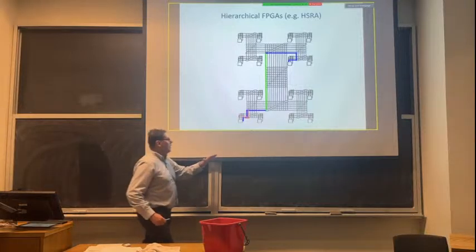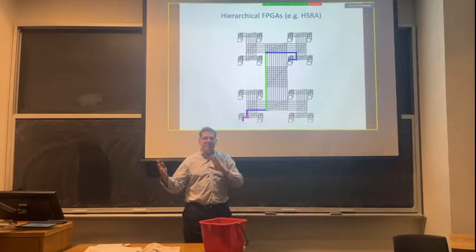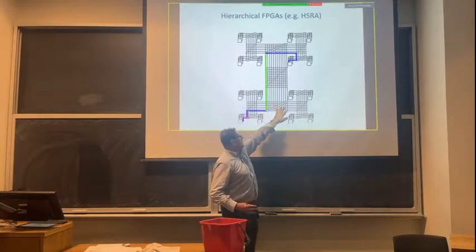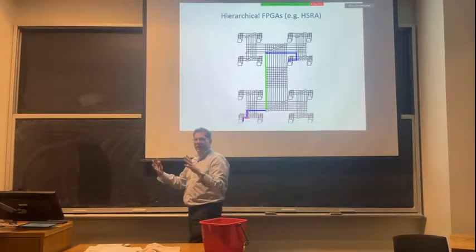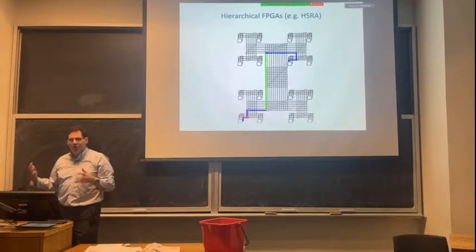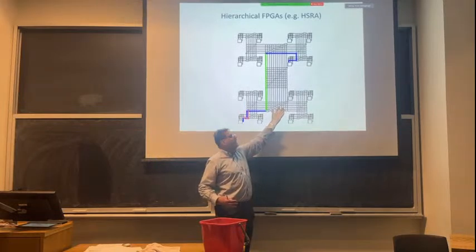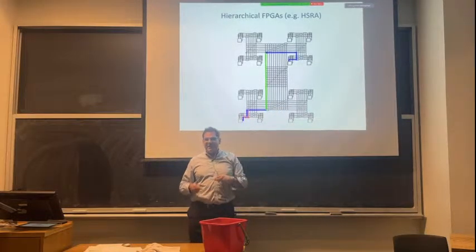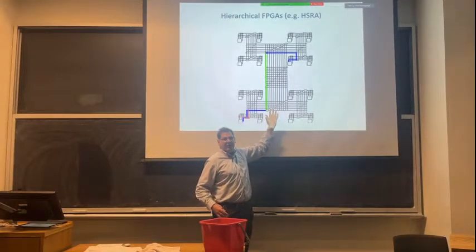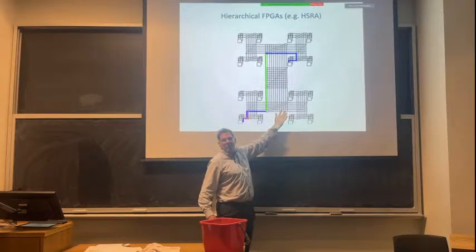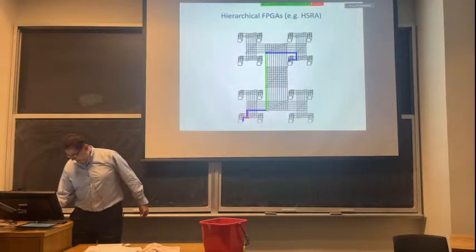Well, we do get a fair number of them. That's true. Although, as I showed before, the total number of wires at this level is less than the total number of wires at level 1, right? Because we're exploiting this hierarchical nature of circuits and the locality that Rent's rule gives us. So I guess you think, well, I should have put fewer in. But then you feel lucky because you feel like customers or designers are going to have good locality in their designs. So this is kind of your trade-off. You do look at these and go, man, that seems like quite a few wires still, but how many do you want to take out? It's risky.